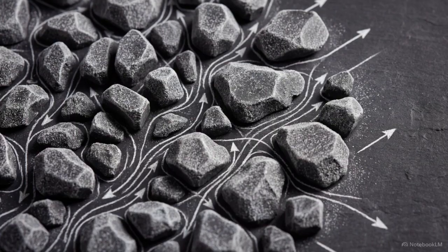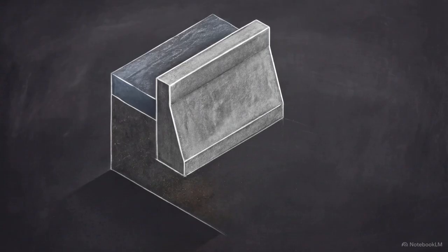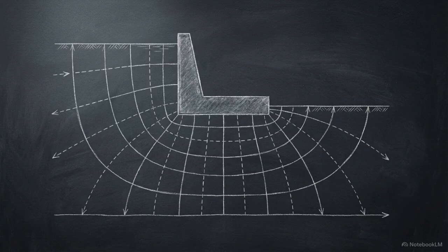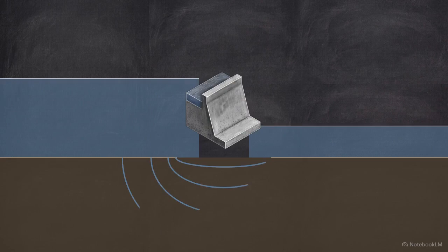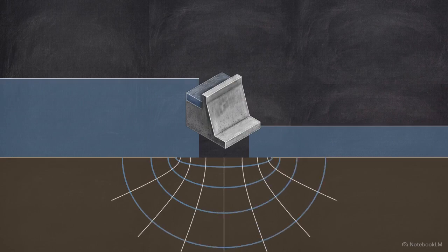Permeability is a metric that defines exactly how easily a fluid can travel through the interconnected voids of a specific soil matrix. Because this underground movement is invisible from the surface, engineers must visualize and calculate the fluid's path by constructing flow nets. Flow nets are graphical representations of 2-dimensional seepage, built using intersecting flow lines. In this 2D cross-section of a dam, the animated grid appearing in the soil demonstrates a completed flow net. It allows engineers to mathematically map the directional vectors and pressure drops of seeping water beneath massive structures.